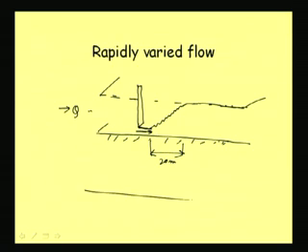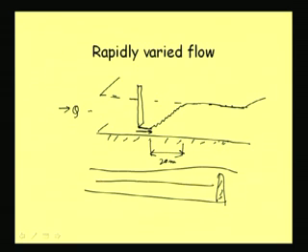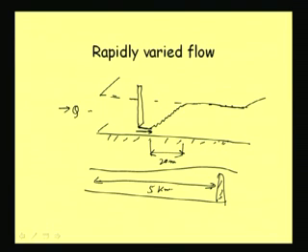And when you talk about gradually varied flow, suppose you are giving a barrier, in practical field in nature it can be of say 6 kilometers, 5 kilometers, in that range. Well, in a laboratory channel we can form this in a very small length also, and of course the dimension will be very small. This distance depends upon the height of the barrier and what amount of flow is coming. All of these are dependent, but I am giving a typical value so that you can appreciate the difference between rapidly varied flow and gradually varied flow.